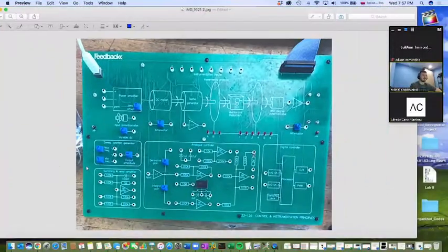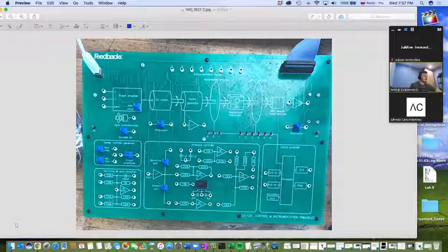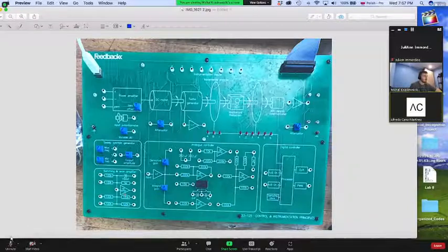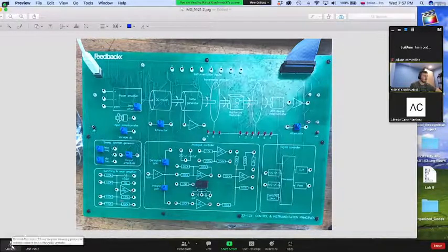Here I have a picture of the board. When we have the feedback coming back from, for example, the 360-degree potentiometer, which gives us the voltage that relates to the position of the motor, it feeds back here and goes into the summing and error amplifier. So these feedback resistors, if we connect them in parallel like this, this is what the gain is, right? This is what the KP would be? Yes, it will be a scalar of that.